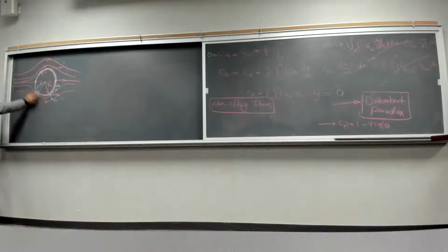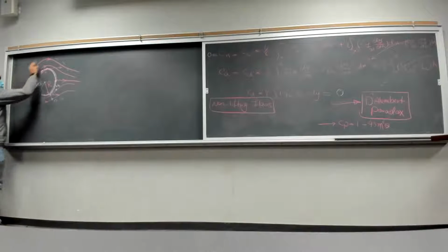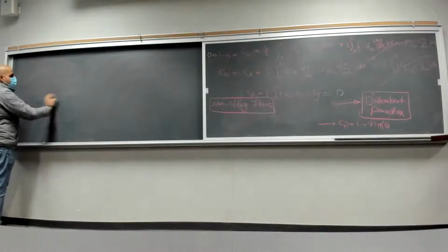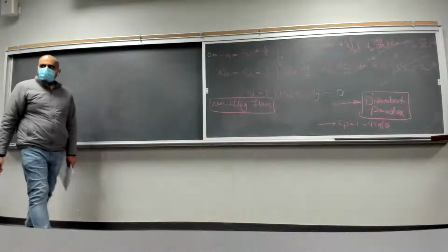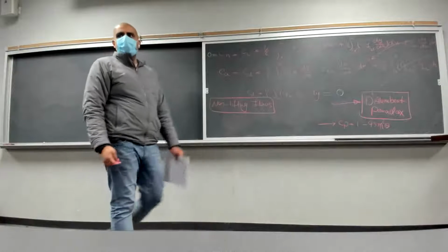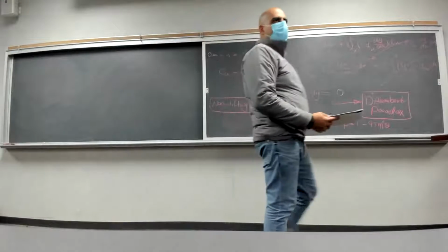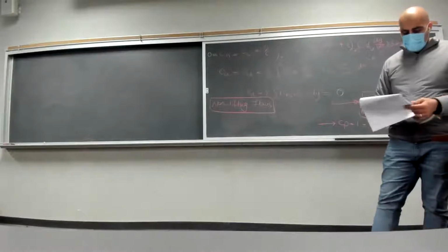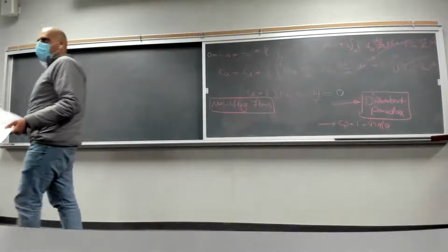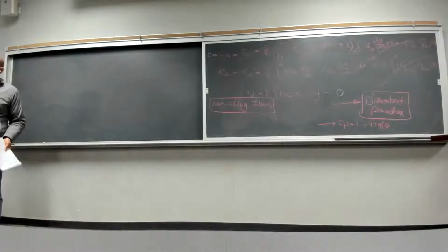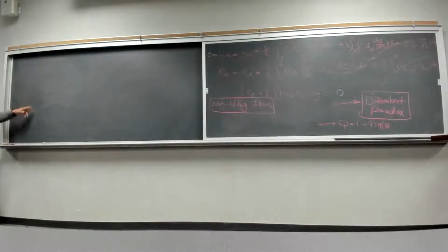So here, for this type of flow, the non-lifting flow over a cylinder, we assumed the velocity distribution was given to us, right? Which doesn't really happen in the real world. What should we do then? How can we find the velocity distribution? We cannot just put flow meters everywhere in this flow, because when you put a flow meter in the flow, you are disturbing the flow.